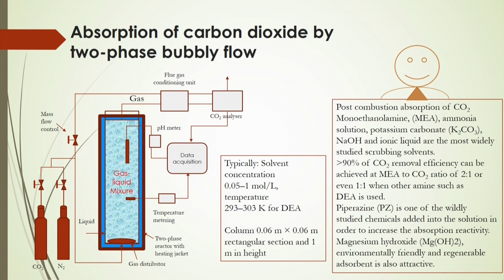Another important factor is the physical properties of the liquid. If you are using a different type of solvent, the gas hold up and mass transfer efficiency will vary according to its physical properties. Sometimes changing the pH of the solution may also affect the absorption capacity. So, this is one important factor.